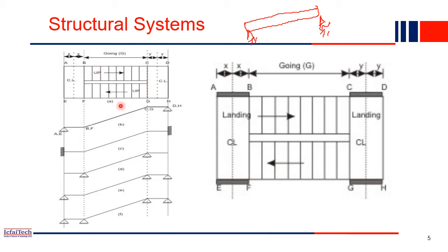As I mentioned, now we'll be dividing this stair into our beam, column and slab portion, right? So you can consider this as a simply supported case, or you can consider it as fixed, or you can consider it as overhanging, like see, this is the overhanging beam, right? So you have one support here, another support here, and a cantilever portion here, the middle portion simply supported, and again you have a cantilever. So this is an overhanging beam you can consider,